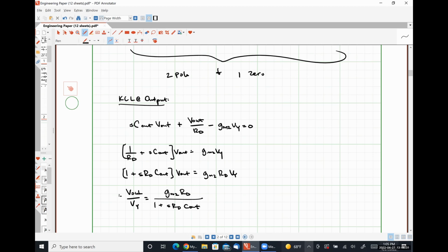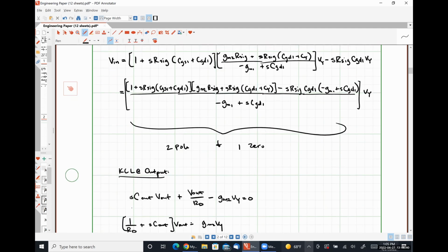So from here, we've definitely determined at least where one of our poles is going to come from for sure. We know what one of our zero frequencies is, or actually our only zero frequency. And our other 2 poles are going to come from combining this into a second order polynomial and then applying the quadratic equation, negative b plus or minus the square root of b squared minus 4ac. That's the quadratic equation, right?